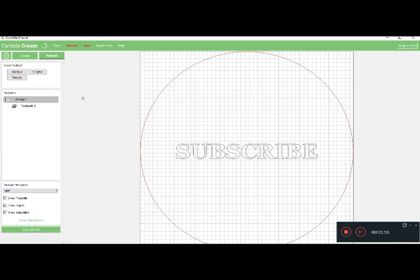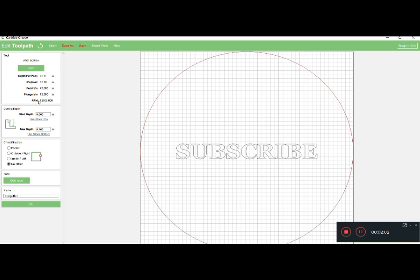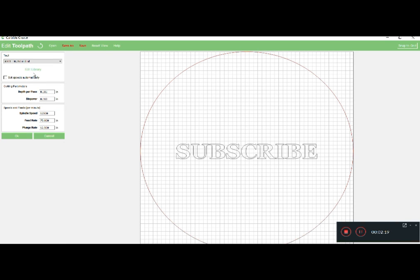So now we created a toolpath of how deep we wanted it. Let's double click on that again and go to edit. There's our max depth. If we wanted a start depth, we can maybe do 1/4 inch, even though that's way too much. We can go 0.100, but that's our stop and start depth. So let's go to edit.